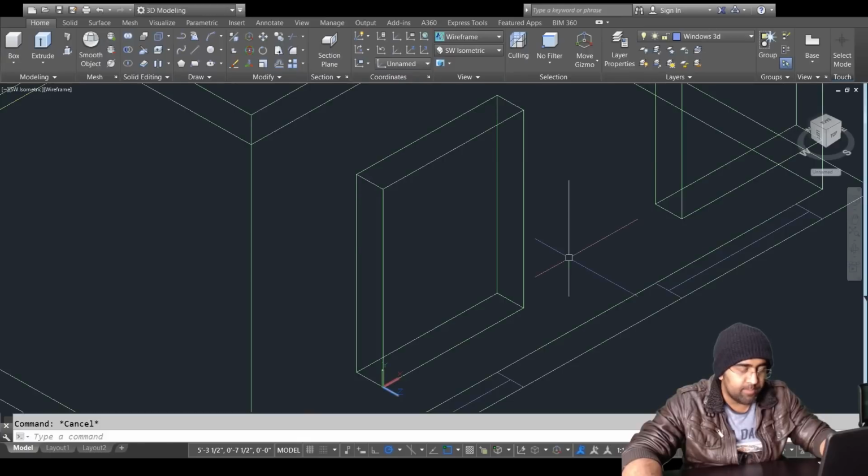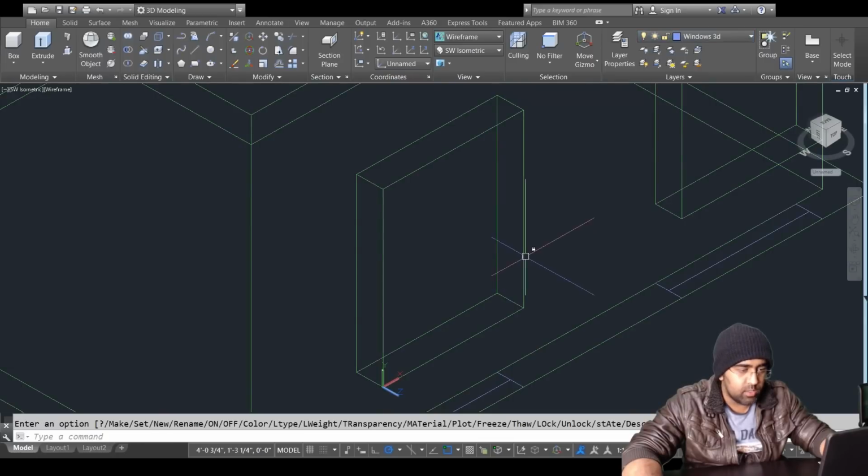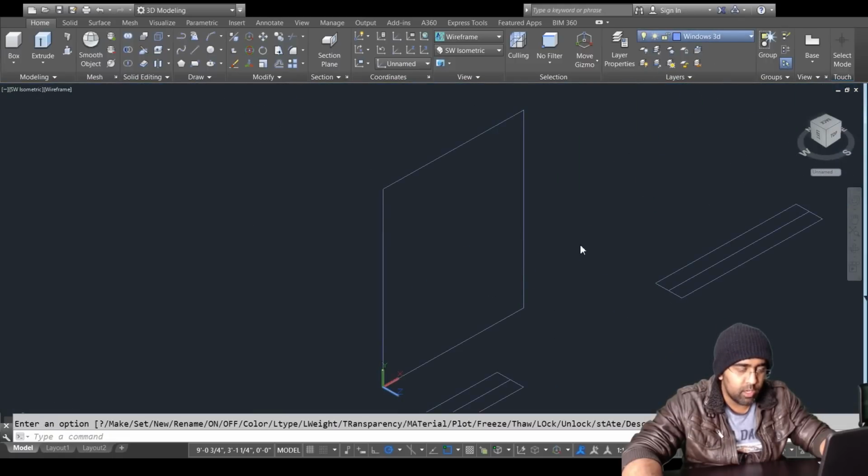So now change the 3D window there. Okay, that's the layer we want. So draw a rectangle, it's gonna draw on there. Okay, so we have that. Now let's go and freeze that 3D wall layer as well. We don't need that to work with us. Okay, let me just turn it off basically. Why can't we just turn it off? Turn it off, we don't need that. Okay, so we have this 3D wall.